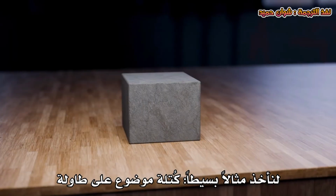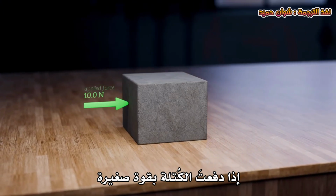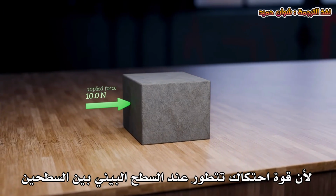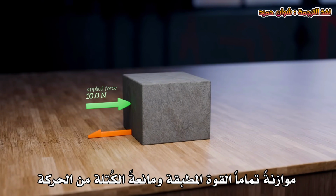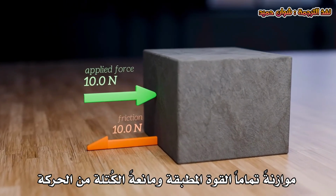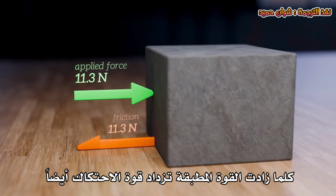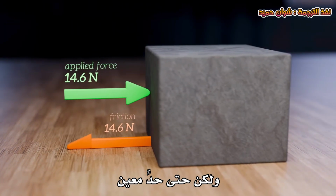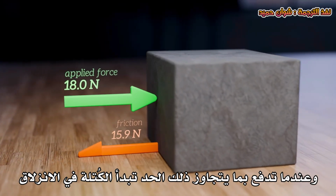Consider a block resting on a table. If you push on it with a small amount of force, it doesn't move, because a friction force develops at the interface between the two surfaces, exactly balancing the applied force and preventing the block from moving. As you increase the applied force, the friction force increases too, up to a limit. Push beyond that limit, and the block starts sliding.